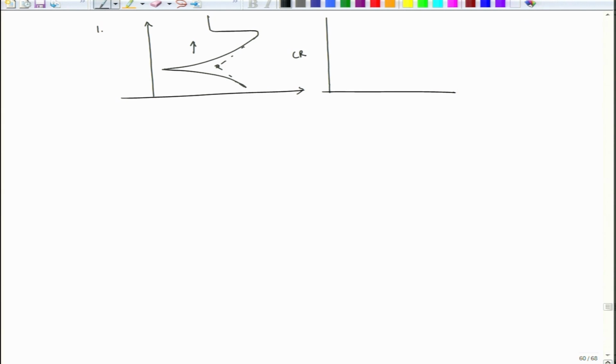So, when we do anodic polarization, this was the Ecorr. In the free corrosion condition, the potential would be maintained at this level. Now, when we take it forcefully to the positive, anodic side, the corrosion rate changes. As we go this way, the corrosion rate increases, reaches a maximum level, then decreases again and maintains a flat portion. So, this is corrosion rate with potential.